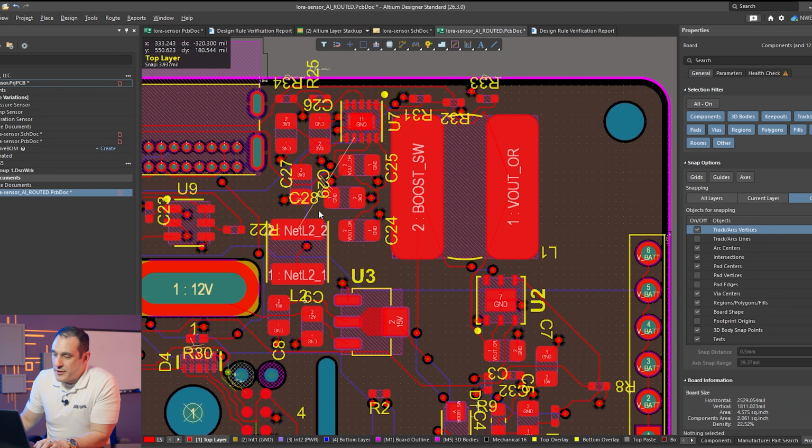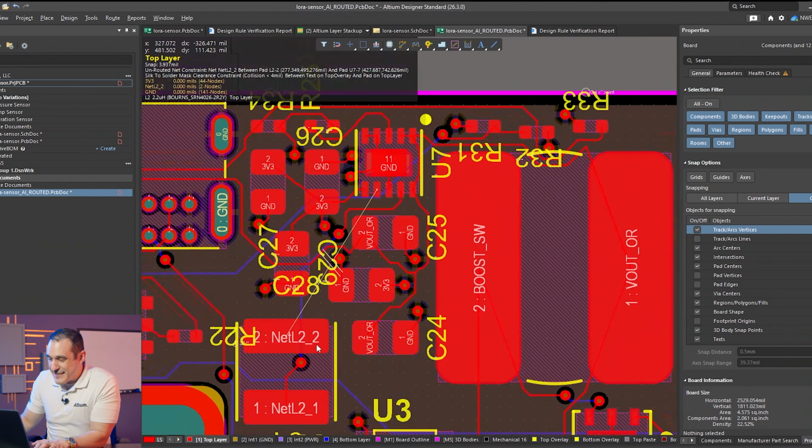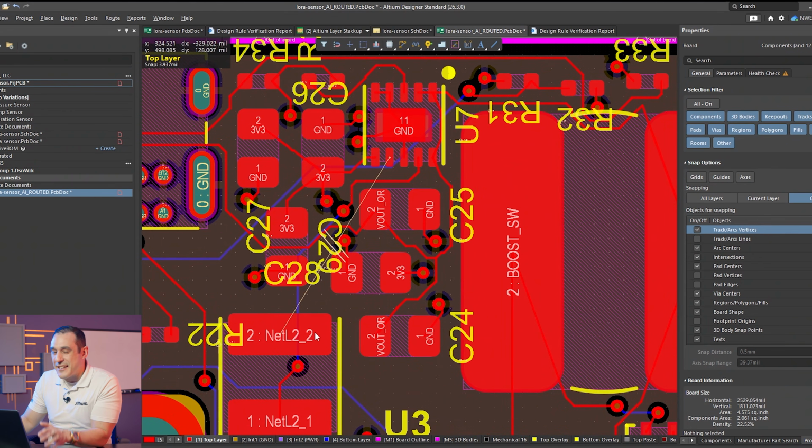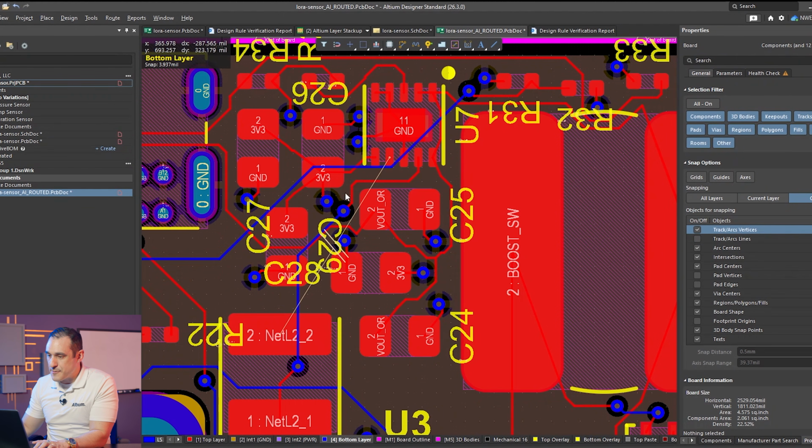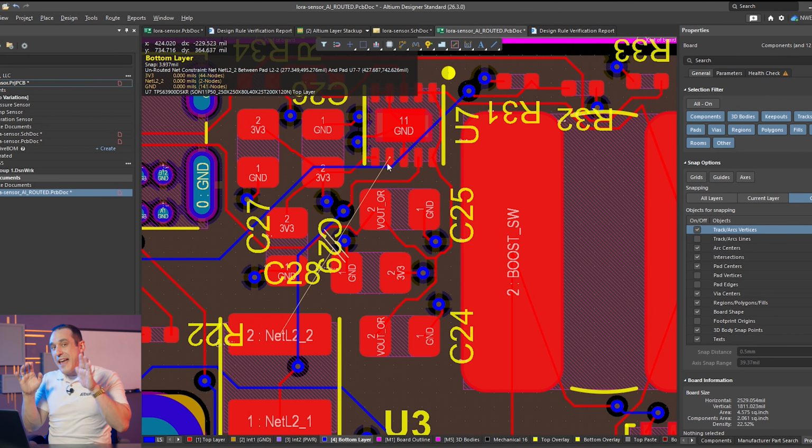It results in an unrouted net. Now this is despite the fact that if I really wanted to, I could actually take a via, drop it right here, and then route a trace on the back layer over to this pad, and then use another via to reach this pin on the top layer. So this route actually could be completed in the current layout, in its current form, despite how horrible the layout is. My earlier remarks apply to this section of the layout as well.